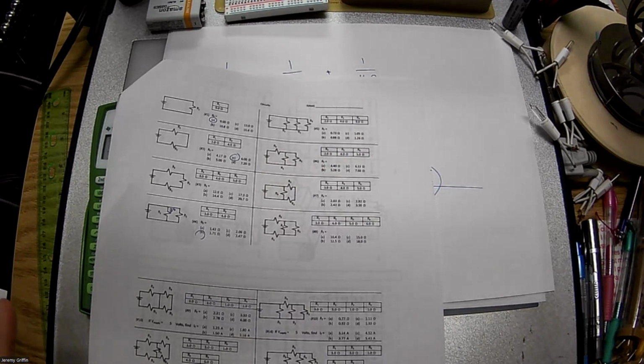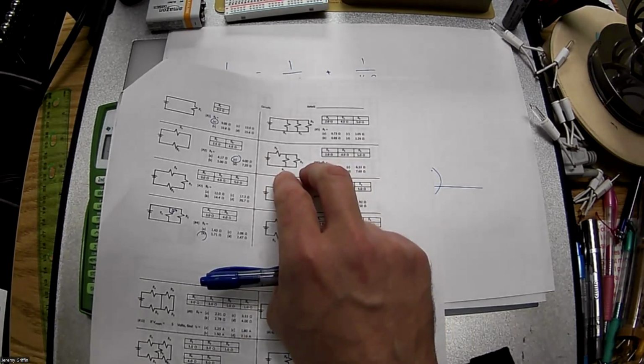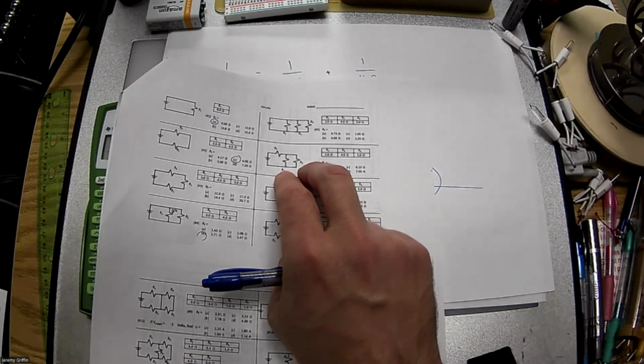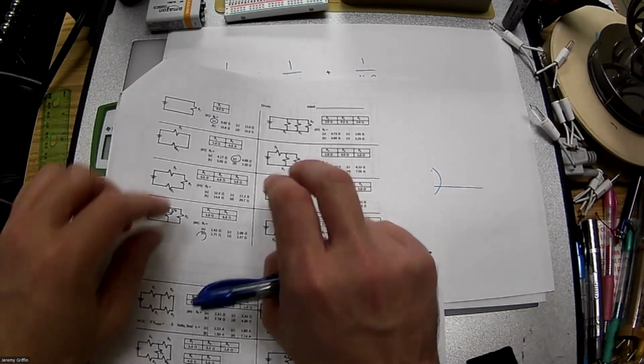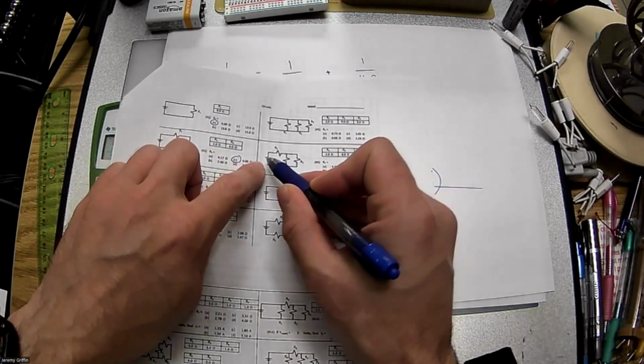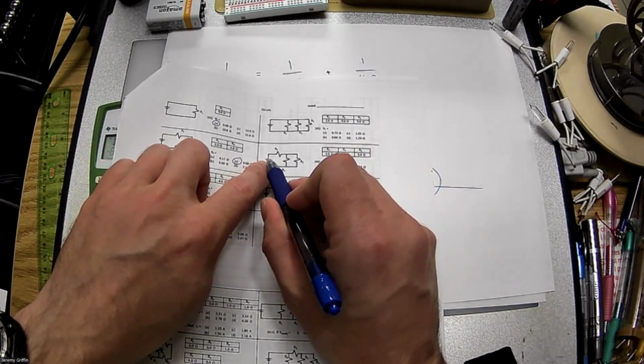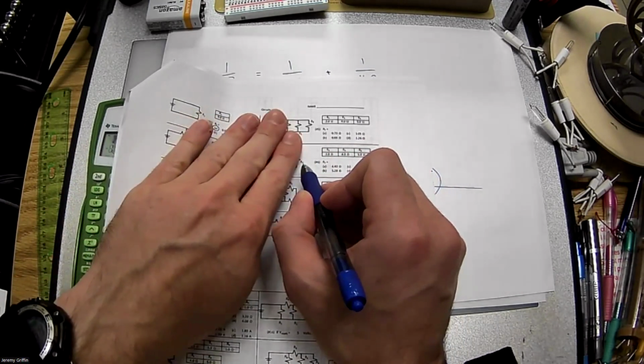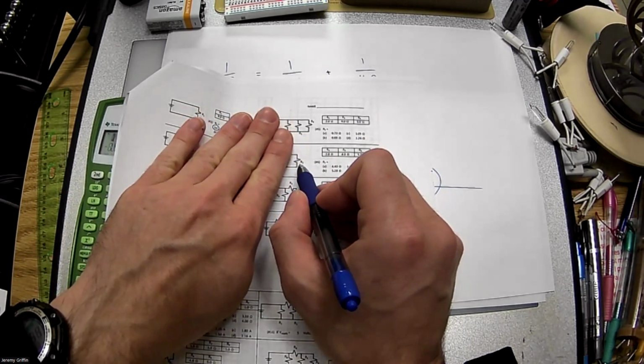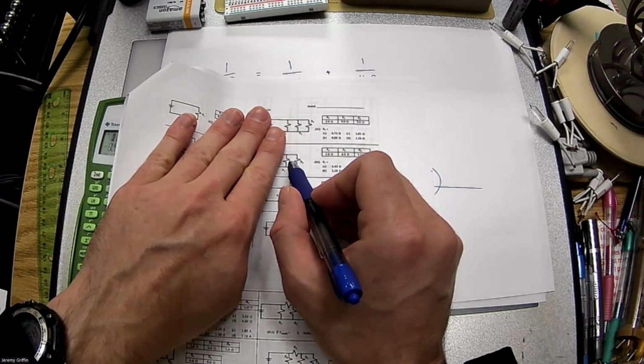So I need to introduce a process to you. Actually, I may have mentioned this process in the last 5 minutes of yesterday. When you get more complicated circuits, there's a particular process that you have to follow. It goes like this: you find your voltage source, which in this case is on the left side of the circuit. You fly over to the complete opposite side of the circuit and you work your way back towards the source, and then you find equivalent resistances along the way.